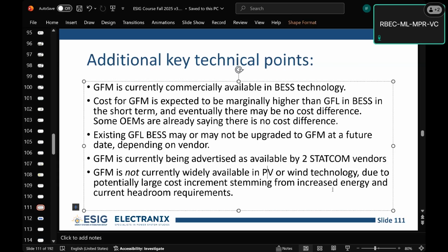we're not going to give you any active power or angular stability, but we'll give you voltage magnitude stability. So you can hold the voltage constant and you get that small signal voltage stability, which will really help you in weak grids. We've seen that in the StatComs without any real energy behind it. So it's basically like operate your voltage source converter controls like a StatCom a little bit, or like a grid forming StatCom. So it's like half grid forming, right?